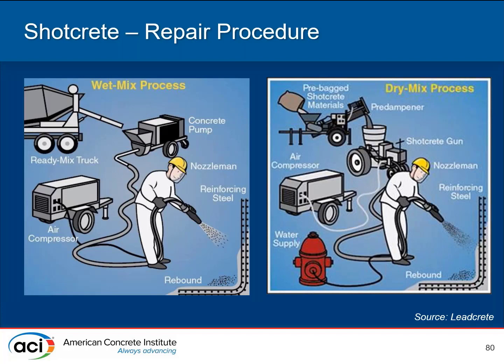It's not so dry that it's not really concrete, it's just a bunch of powder, but it's not so wet that it sags and sits and doesn't have the properties you need. Generally, for the way I do it, shotcrete I think is a very good process, but I let the contractor figure out which is the right one for them, for the way they do things for that situation.